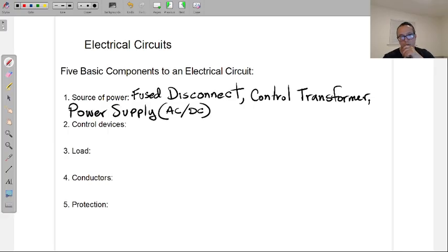Again, stepping down that voltage into DC circuits. One is done for safety. I think the other more likely reason is just cost. When it comes to component parts that require this electricity in motor control circuits, the lower the voltage, the cheaper the component. Not cheaper as far as it being cheap and not good, just as far as cost to build that component itself. The higher the voltage, the heavier duty the internal stuff has to be on things like motor starters and relays and stuff like that.